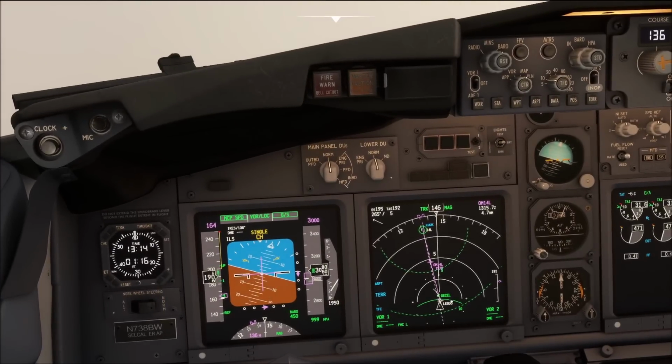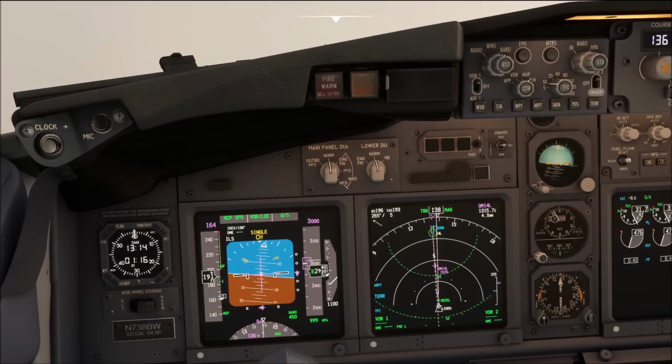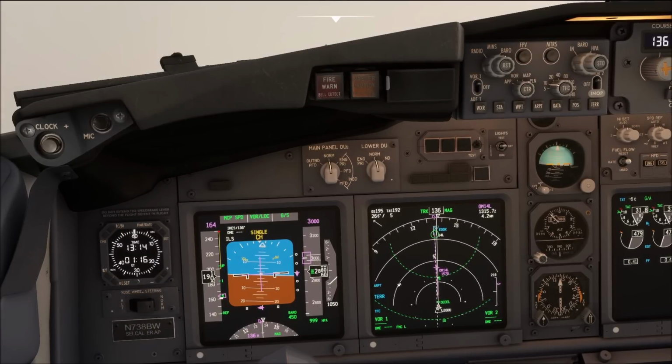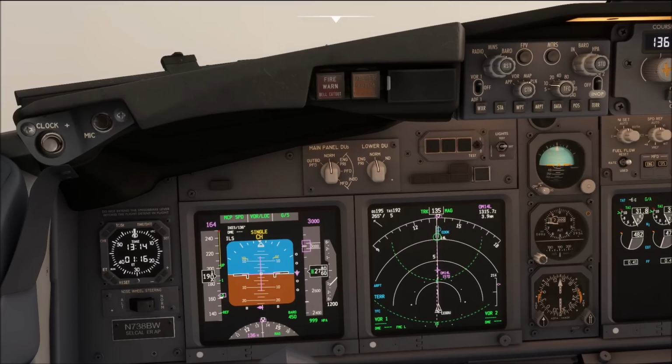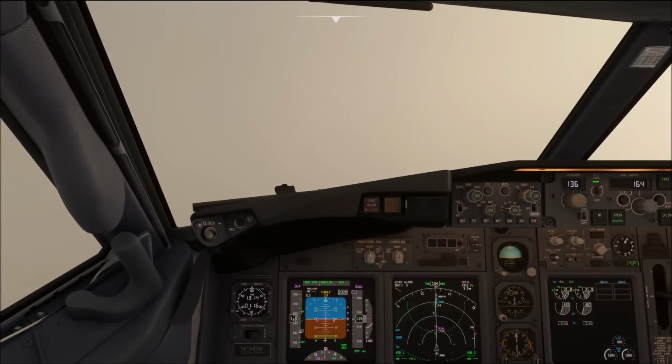Be aware, we have passed to beam our final approach fix and see how our altitude has been higher than 3,000 feet at that position. I do have to say, in Microsoft Flight Simulator at the moment, the effect does not seem to be as great as in real life. So in real life, when you're passing the FAF over here, at temperatures like we have them right now, you would really see something like 3,300 or so on the altimeters. On the sim, that does not seem to be quite the case yet. However, there is some sort of an effect, and Asobo is likely still working on it, so that's why I do already put great emphasis on including these cold temperature corrections at the moment.